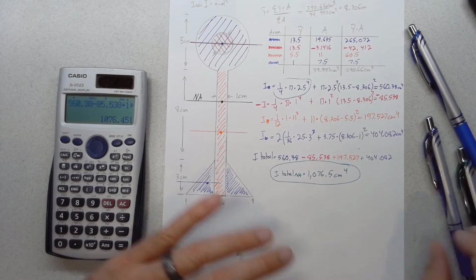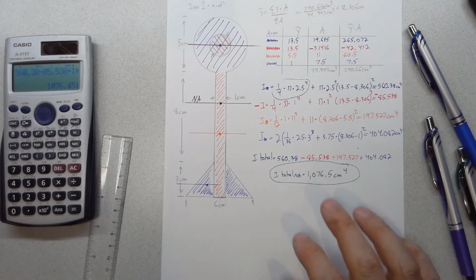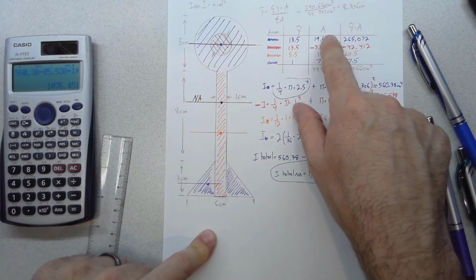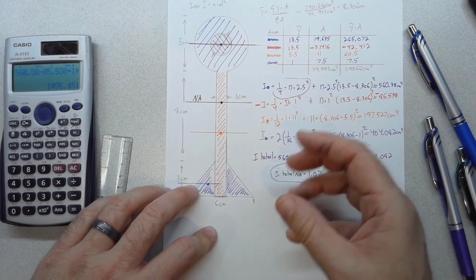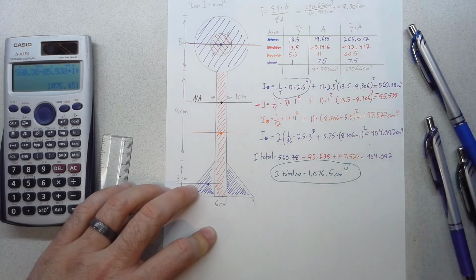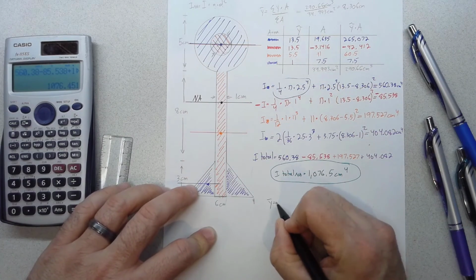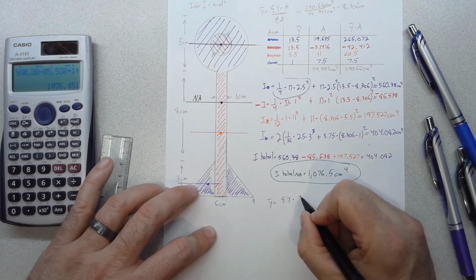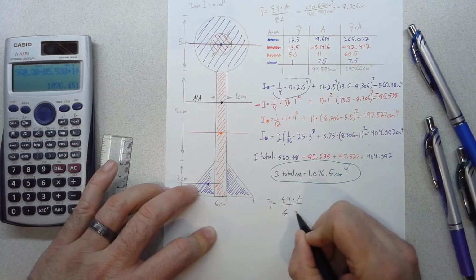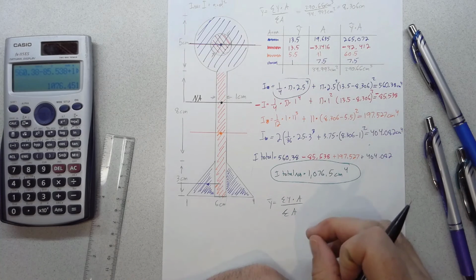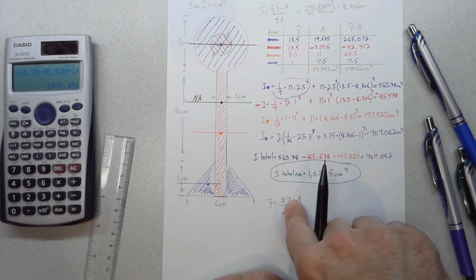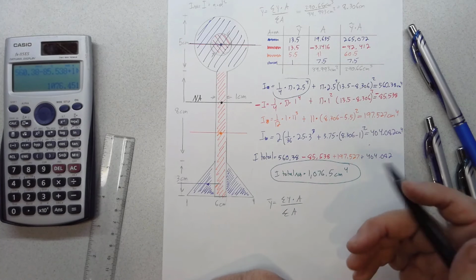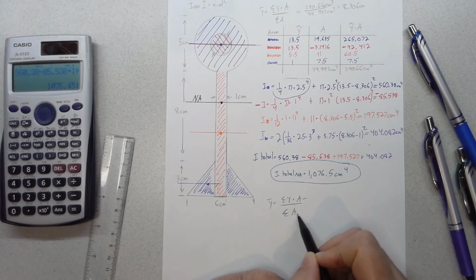So you can see you can take pretty much any weird geometric shape and find, first you find its centroid using first moment area basically, and then you find its moment of inertia, what we call the moment of inertia, which is really the second moment of area. Another way of saying I, we haven't really talked about this, we say y bar up here, y bar equals the sum of the individual y times the area over the sum of the areas. That's, like I said once before, that's really the first moment area about the neutral axis, right? We're taking an area, multiplying it by a distance. So if you think back to moment is a distance times a force, this is kind of like the moment of an area divided by the area.